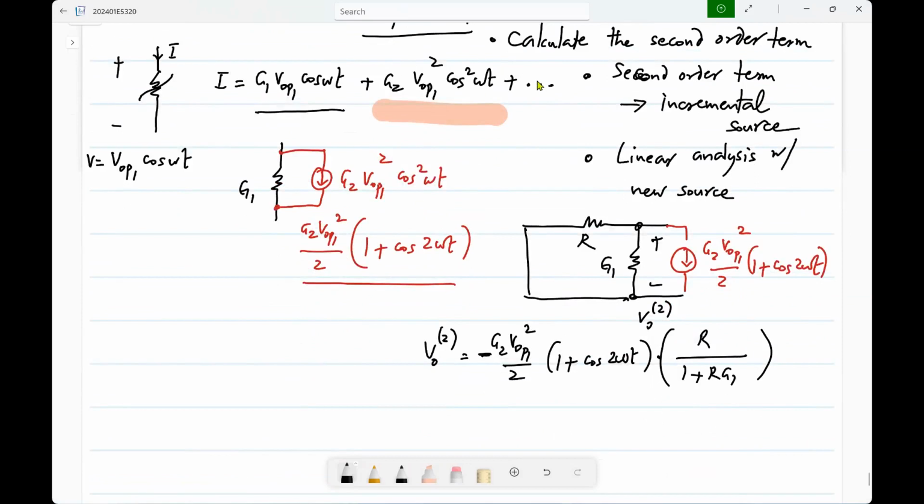First, there are two terms here. The first term here is constant, right? So that's like a DC offset term, and that is characteristic of even order nonlinearity. It's only when you do even order. If you remember the trigonometric expansions, if you have even powers of cos or sine, you will have a constant term. If you have odd powers of cos or sine, you will not have that, right? So this DC offset, this DC shift is characteristic of even order nonlinearity. I mean, that's just an aside, but anyway, that's what you will see.